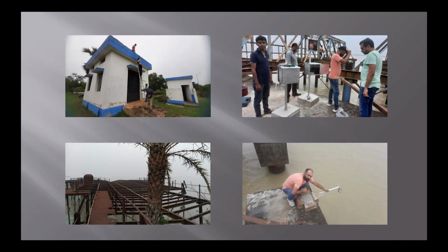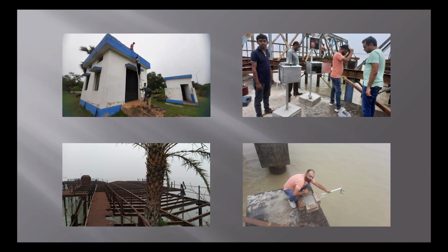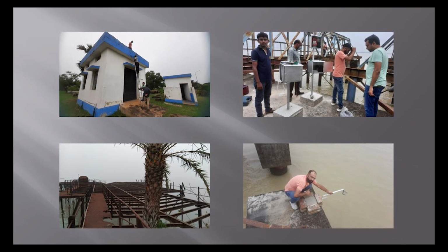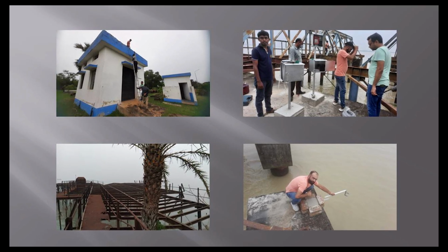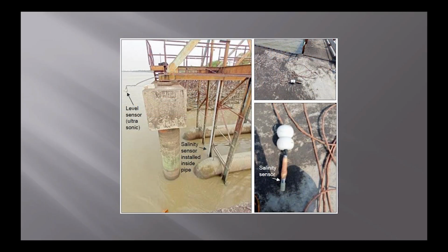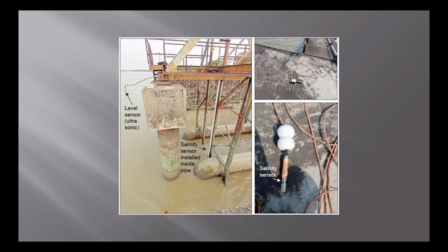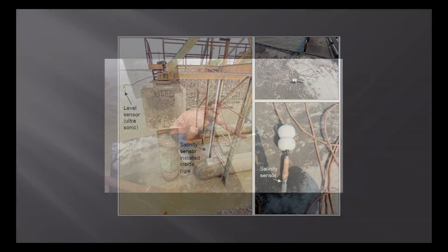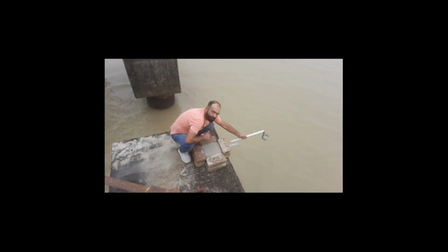The other challenges were that the intake structure was not in satisfactory condition, clamping of instruments to the bridge was in a vulnerable condition, and minimum draft in the dry season was an issue. Hence, there was a requirement to hang out the cantilever frame structure more, which was previously not estimated.